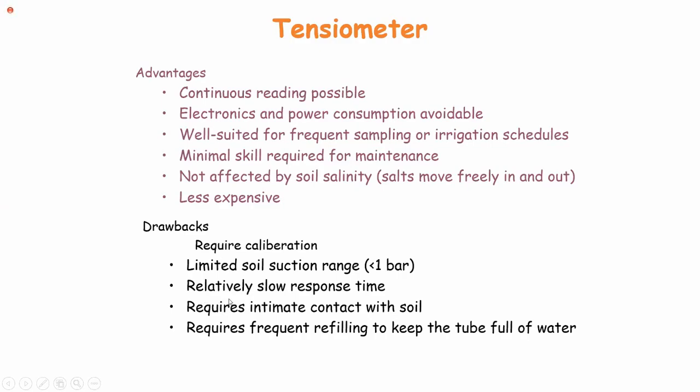Then relatively slow response time. It will not take much time to measure once you get the calibration curve, you can easily calculate. It also requires intimate contact with the soil. So when you install it, you should be very careful. There should be intimate contact between the soil and the instrument. If you do not install it properly, maybe the measurement will be inaccurate.